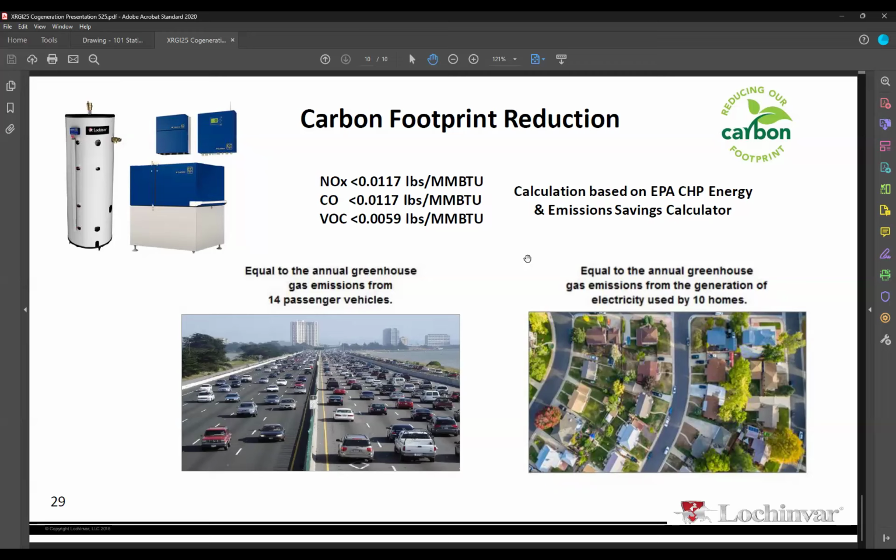But yeah, there are even further technologies out there. There were even things in development from different manufacturers, heat pump combi boilers that can be instantaneous. I just try to arm people with some of the silliness: if someone says there's an instantaneous heat pump, question it. The reason we oversize the storage is so that we can reduce the generation requirements of the heat pump, so we can shrink it, because that's the costly item.